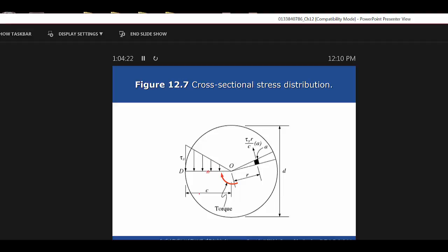75 millimeters again. That's the max out at the end, isn't it? That's why you have to use the 75 there. Because it's like, well, wait a minute, why wouldn't I use the inside diameter divided by 2? Well, you're trying to find the max, and the max is out at the outside diameter, isn't it? Make sense? So that's why you use the 75 there.